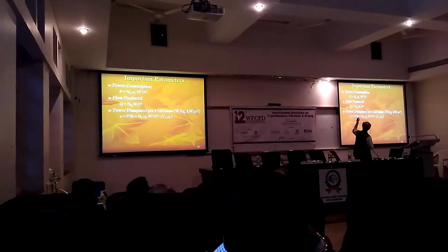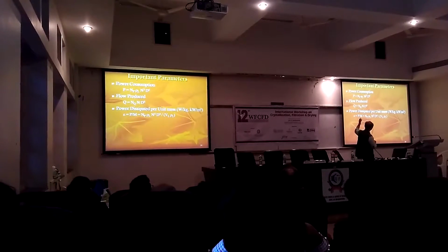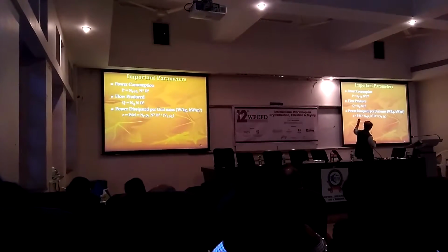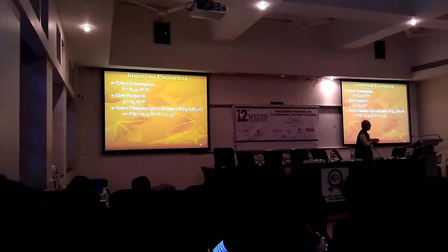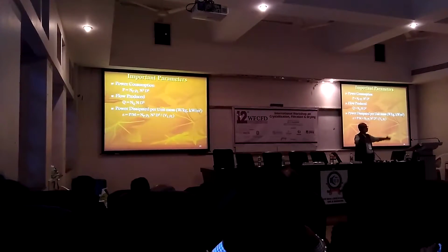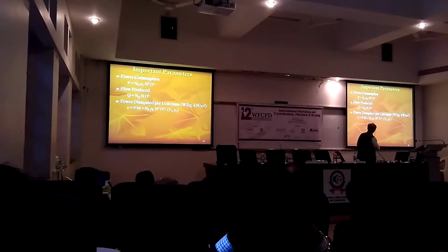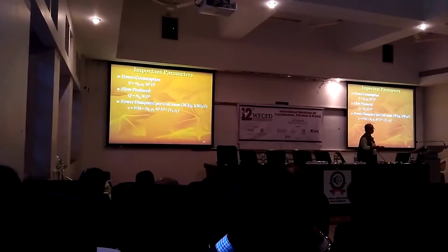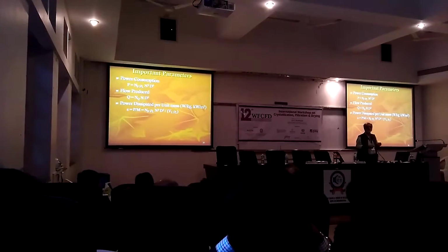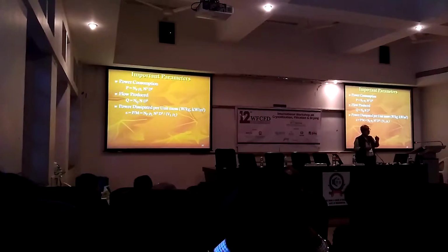the power which I am going to utilize. So this is the power number, density, operating speed, diameter. This is the flow number. This is a kind of a liquid flow which is getting generated, the overall agitation which is provided, and the power dissipation can be calculated per unit mass, because usually this is the scale-up criteria which is used by the industry most popularly. Power dissipation per unit mass.